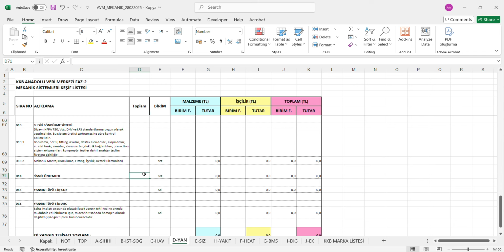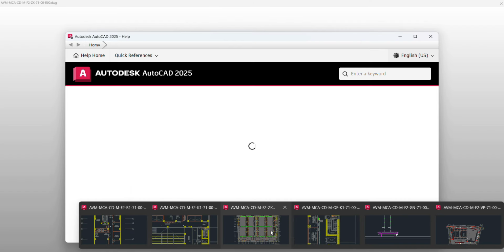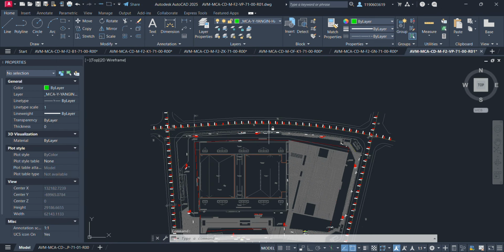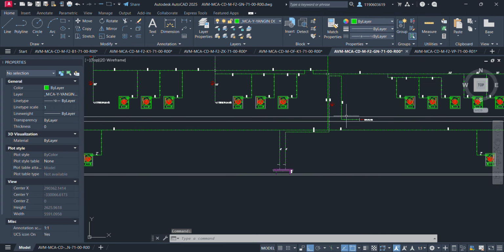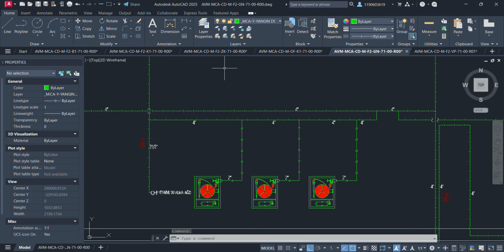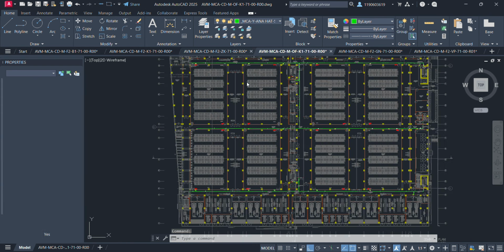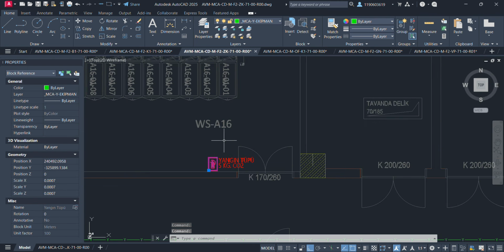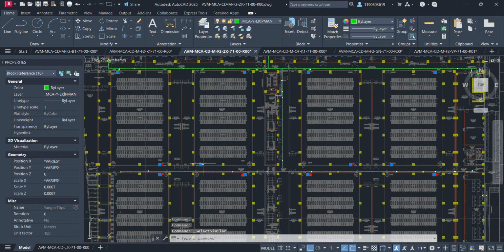Materials. Collectors are made from corrosion-resistant materials such as stainless steel or galvanized steel to ensure durability and long-term performance under harsh conditions. In fire protection systems, bronze or steel collectors are commonly used due to their resistance to corrosion caused by water. Design. The collector should be designed in a suitable manner to ensure fluid flow is efficient with minimal resistance. The design depends on the type of fluid or gas being transported and the pipe size.